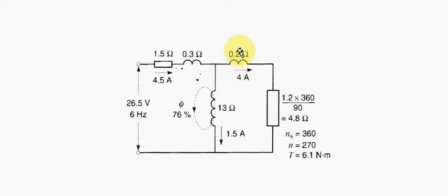This value here obviously drops, but this is more to do with the frequency set up in the rotor. Okay, I don't want to go into that, but bear in mind that the rotor frequency here, the actual electrical frequency set up in the bars, is not the same as this frequency here.